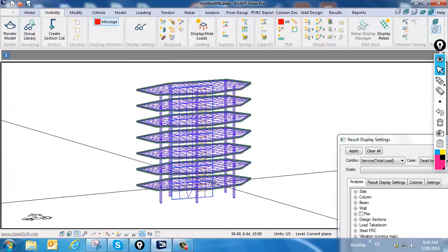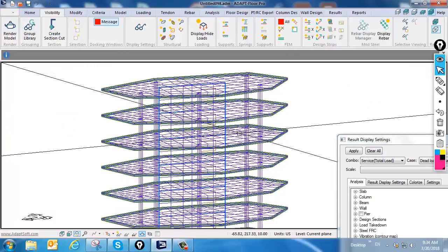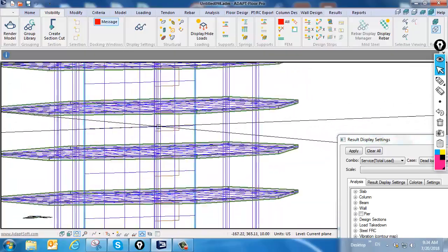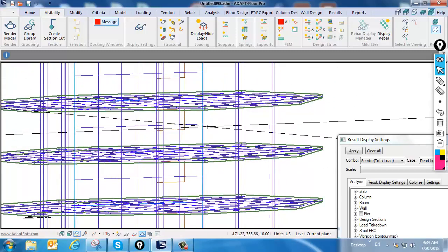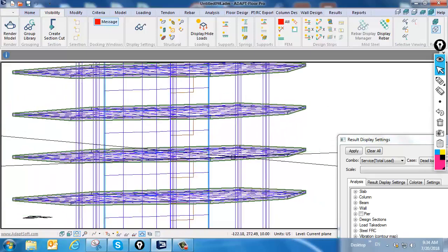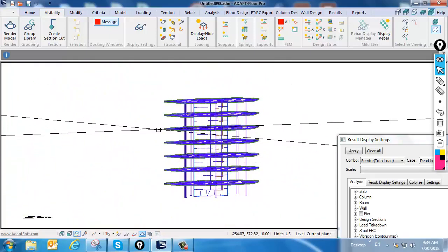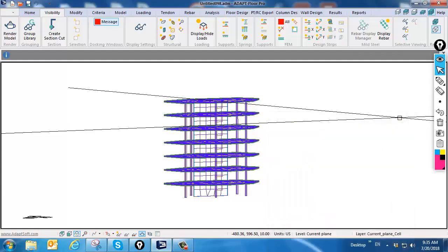It's very linear. All of the shells are of uniform size. This is the old meshing algorithm that's being used for meshing, and you can see that the walls ignore the openings. The wall meshing ignores the openings. The mesh just goes right through the opening. It's as if the opening is not there. And that's one option. If you want to take advantage of the advanced options, we have the ability to do that and to have openings considered for wall meshing.